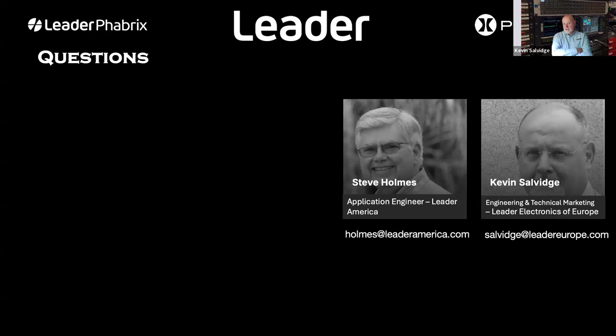Lots of those will use the payload ID, so that when they switch from HDR to SDR, it switches the monitor over as well. They're probably using a grade 1 reference monitor that can do 2020 HDR, whether PQ or HLG, but can also be switched down to 709 SDR. That's where the VPID information comes in.